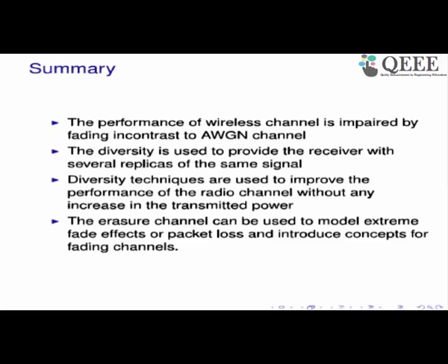If you have a frequency selective channel, it can be easily taken care of by going to MIMO, because from a MIMO perspective, the frequency selective channel becomes a flat fading channel. So that's why this model is sufficient. Time varying nature, I have told you, because in most practical cases during the duration of interest, for multiple transmit symbols the channel is going to be constant, so it is practical to assume that the channel is constant.